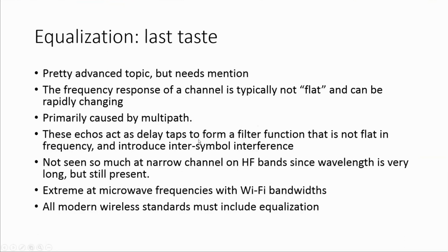But if you're outdoor, where the echoes might be from a mile or 10 miles away, then much narrower bandwidths can have this. Where you would experience this, at least us older people, is in the analog FM TV days, or analog AM TV days, when you had multipath bounce off a building, it would give you shadowing. That's exactly what multipath is. It's a really, really bad problem for data communications. I guess I'm harping on this simply because it's frequently ignored by people that don't know about it, and they propose these crazy schemes that they think are going to work great, and they completely fail, and eventually they figure out why. This is multipath.